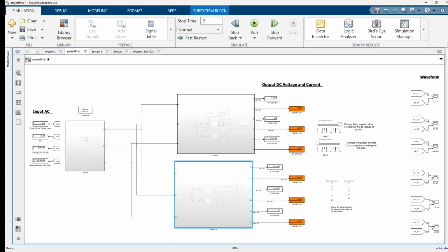Now why do we use two different transformers? So that we can isolate the outputs of each secondary. This will ensure a full electrical isolation or galvanic isolation. These transformer ratings were selected by accounting for the real power demand, harmonic distortions, displacement power factors, and we also considered 200% overload conditions.